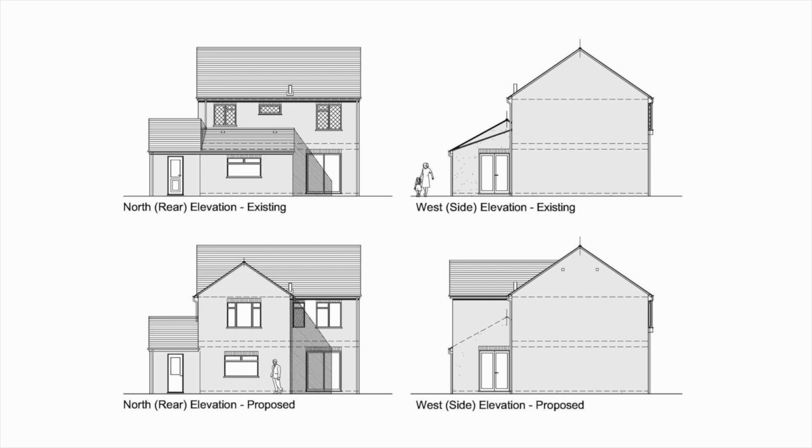A very simple drawing, but at the same time, pretty good with line weights. The things that are closest to us are going to have the thickest line weights. The things that are further away are going to have thinner line weights. This one also shows where the floors are. That's a hidden line. So it's a good use of a hidden line so we understand where those floor breaks are.